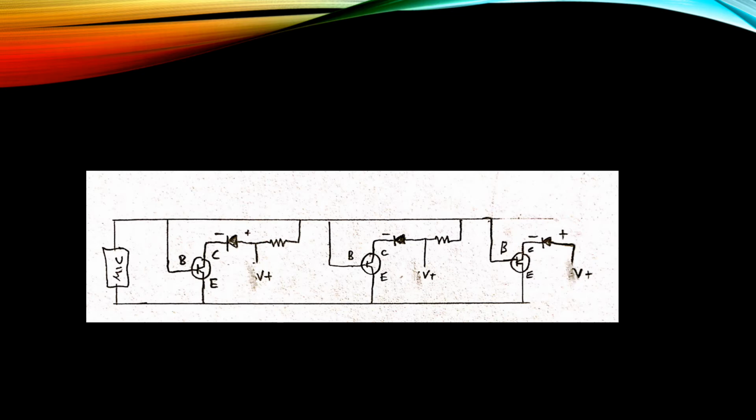So how does this device work? The mic picks up the sound signal and converts it into a voltage signal, and the signal goes to the base channel in the transistor, which opens the channel between the C and E, the collector and the emitter. So more current flows through the circuit, and the lights will turn on. When there is no sound, there will be no signal going to the base and the lights will be off.